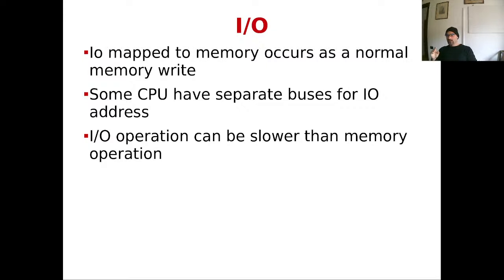Okay, now basically we know at electrical level what happens when we read and write on memory. How do we deal with peripherals? Well, the simplest way is to map the peripherals in the address space of the platform, which basically means we address a peripheral as if it was a specific memory cell or a specific bunch of memory cells, which are interfaced with the memory bus exactly as with the memory, which means address, data and control exactly as if it was a RAM chip, right?